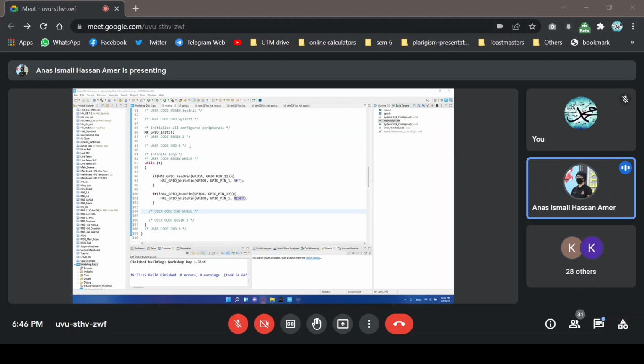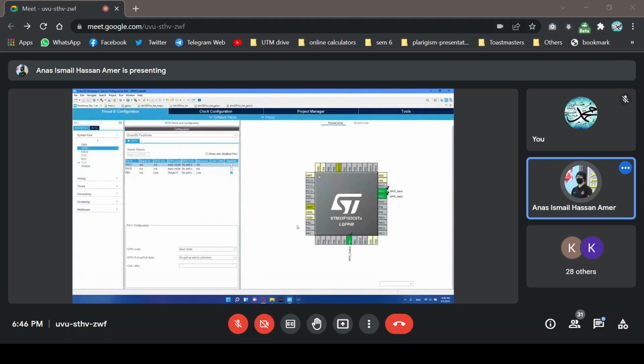So let's revise just briefly. For this screen, we selected P1 as an output because we will need to send the voltage to the LED, which is an output compared to the microcontroller itself. And for the push buttons, we've selected them as inputs, as they provide the voltage, we want to read their value. So we've selected them as inputs to the microcontroller itself.